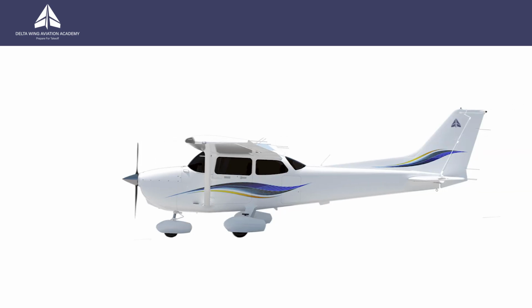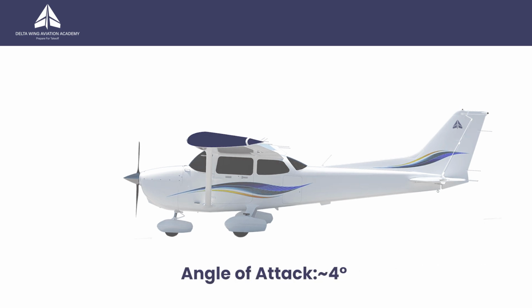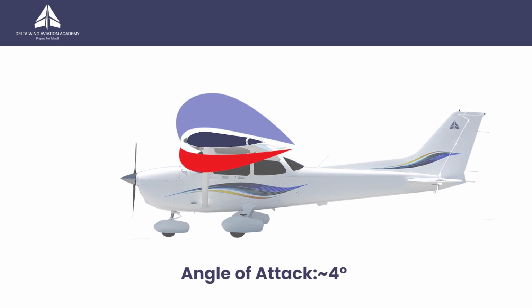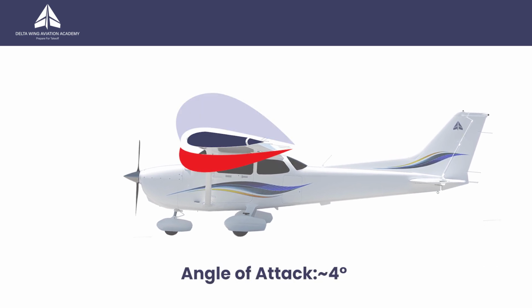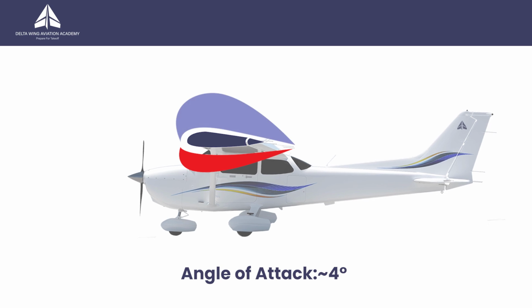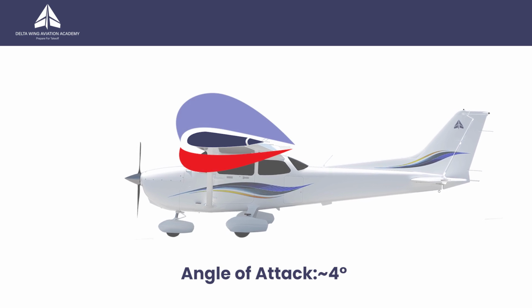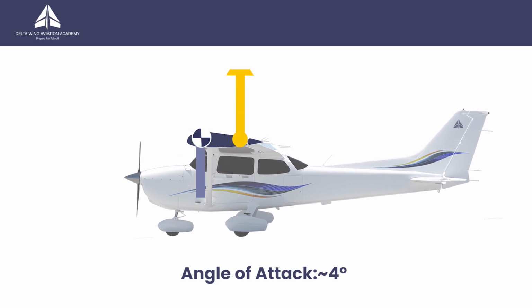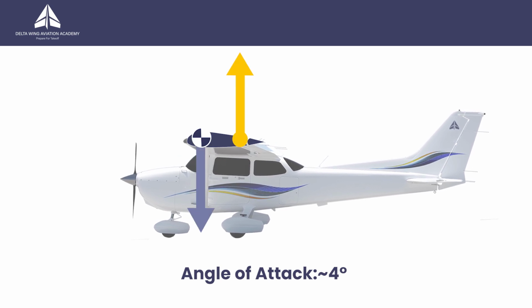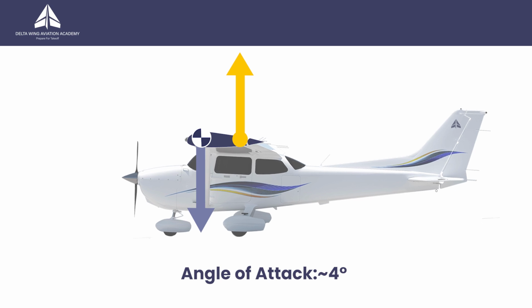In flight, the lift generated by the wings is the product of local air pressure changes. Lower air pressure on top, pulling the wings up, and higher air pressure below, pushing the wings up. For demonstration purposes, those lifting forces can be combined to act from the single main point shown here by the lift vector called the center of pressure.